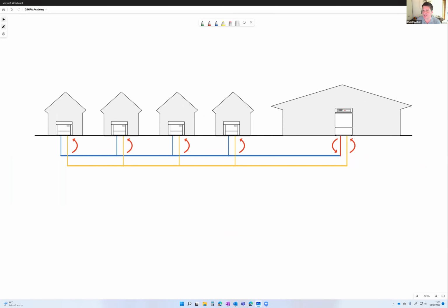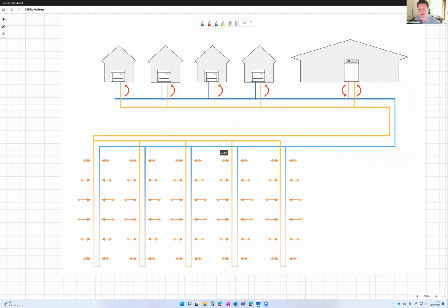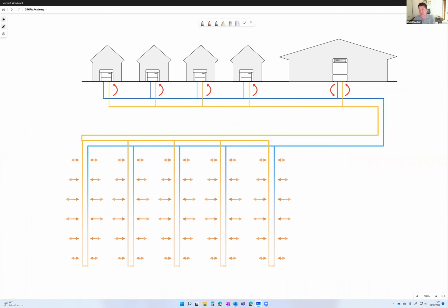And if we had a really nice thermal balance all year round, we could just leave it at that. We could just connect these buildings in and move heat around throughout that heat network. But obviously the chances of that remaining in balance all year round is pretty slim. Okay, so in that instance, your ground loop becomes your energy recovery medium. It doesn't only recover energy, but it recovers energy instantaneously, it recovers energy interseasonally, and it takes away the excess or gives you the deficit.